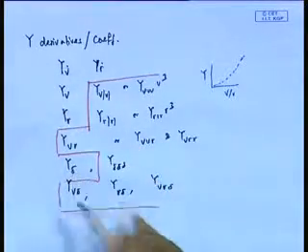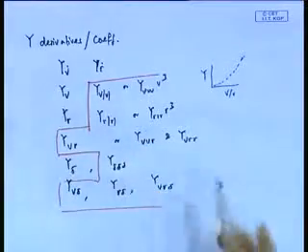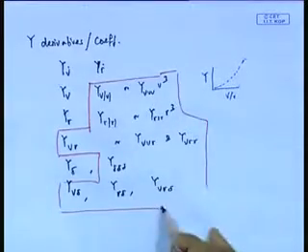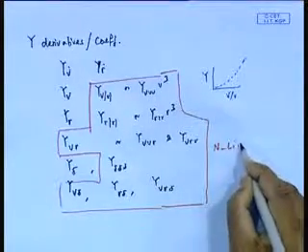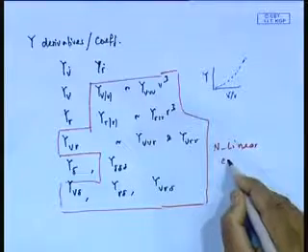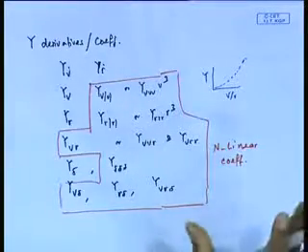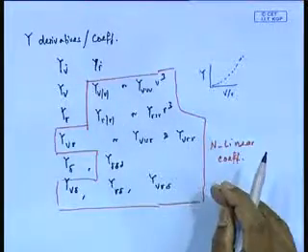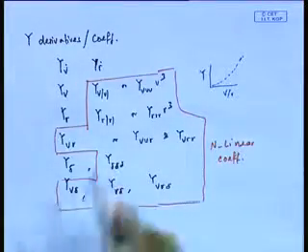This is linear, these are nonlinear coefficients. Okay. Same thing will happen to n. In fact, one can keep going progressively more complicated, because I only take y as a function of v and delta, but if you take also roll motion, then two more parameters come, phi and p, roll angle as well as roll motion. So, there will be many more derivatives that will come, that depend on these.